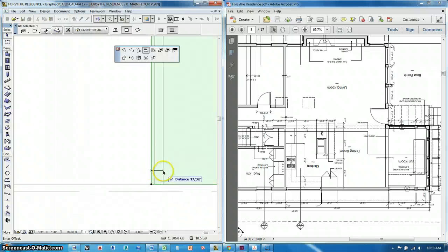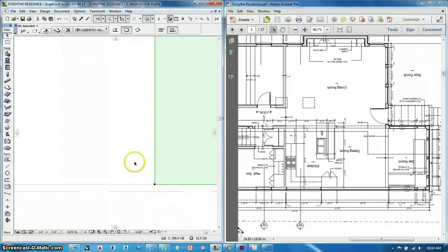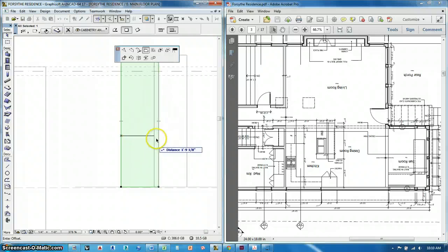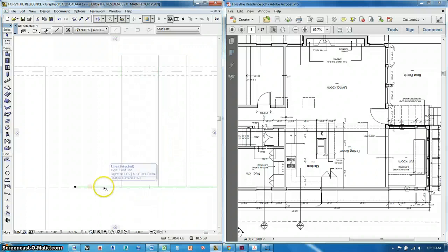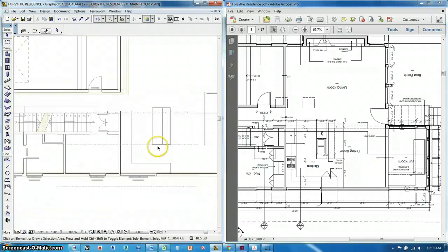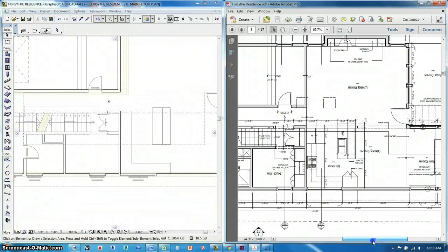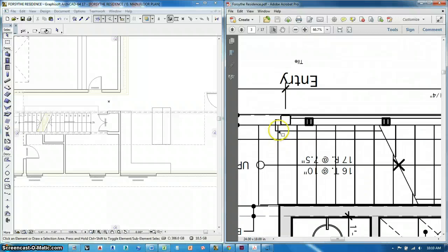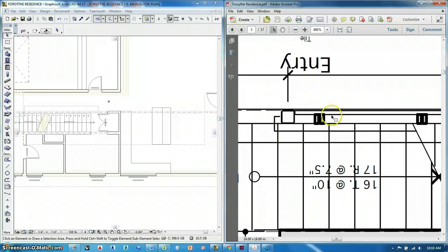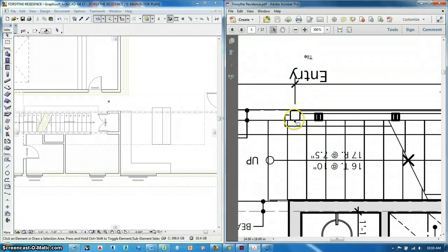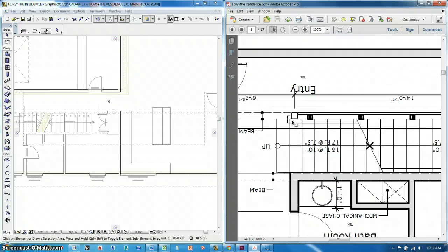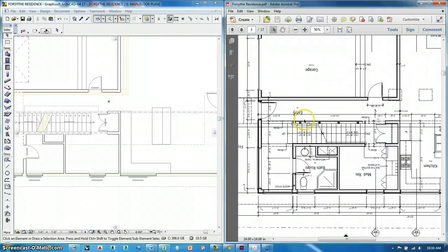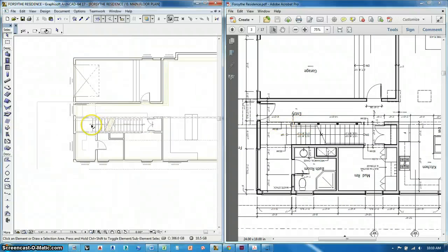Okay. Looks like I messed this up a little bit. I'm going to offset that edge. Let's see, make sure that's the one I got right, though. Yep. Okay. And delete that line. There's my kitchen island. So the last thing I want to show you is how to stick some of these posts in place. So the posts here, these are these posts right there. It looks like these posts are the same width as the beam. So they're 5.5, and it looks like they're square, 5.5 by 5.5. And they look like they're a steel post, but we can assign the material later.